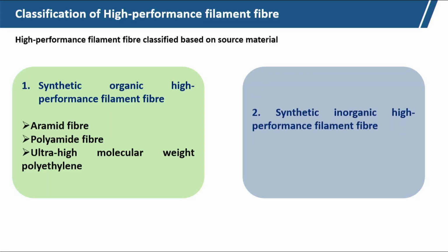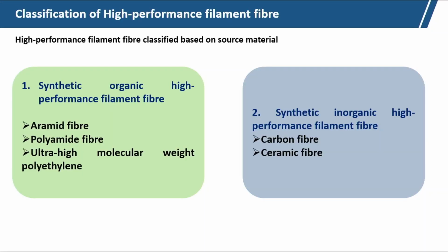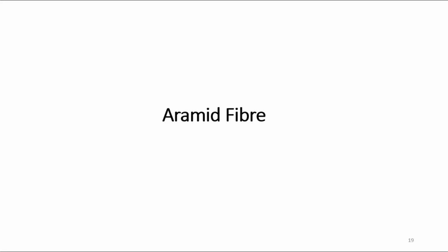So, organic origin is aramid, polyamide and ultra high molecular weight polyethylene, and the inorganic origin, that is synthetic inorganic fiber, is carbon fiber and ceramic fiber. These are the inorganic fibers we get in filament form.